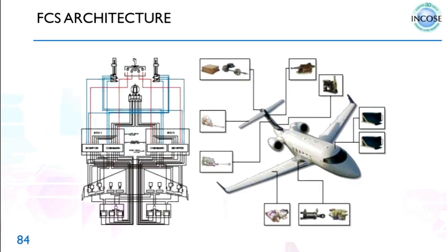And then you have to have an architecture. So this is the pilot controls here, and that goes to the computer systems, and that goes to all the actuation systems. The feedback comes back, and then there is a display panel. The whole aircraft control system is complicated.